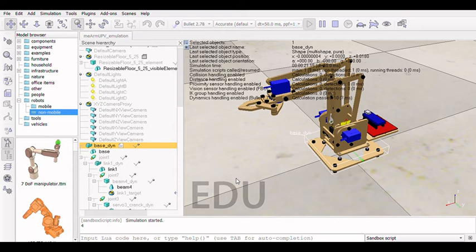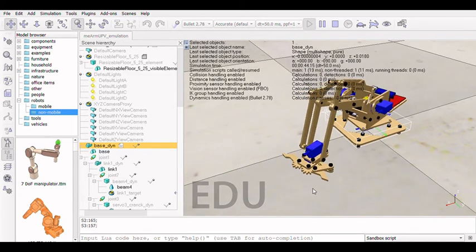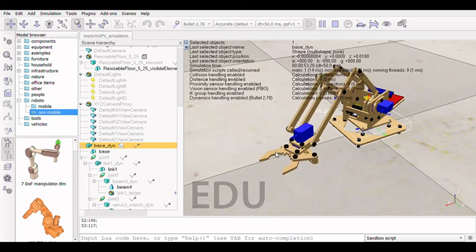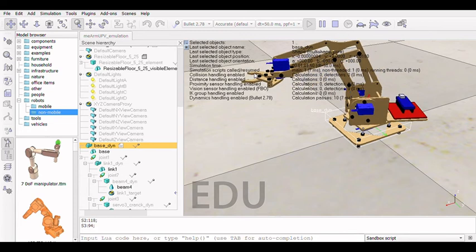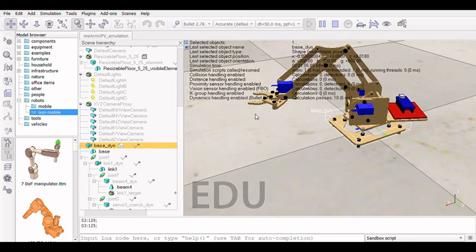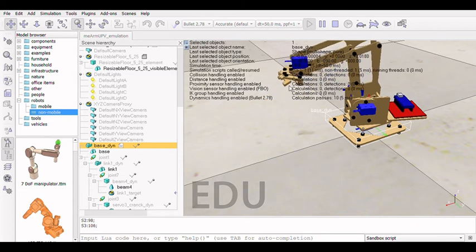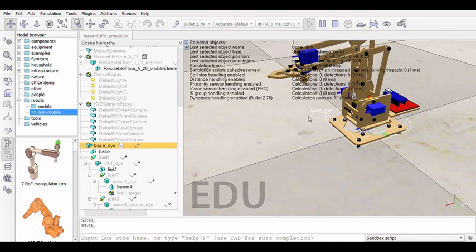Now we will see how the pick and place application behaves in the simulation. So let's start. First of all, the robot must move close to the object, but with an offset. It opens, moves closer to the object, and grabs it. Now it elevates it and moves near to the position where it will be left, but again with some offsets so that the movements are really safe. It leaves the object, and now it gets farther from it, closes, and goes back to the initial position.